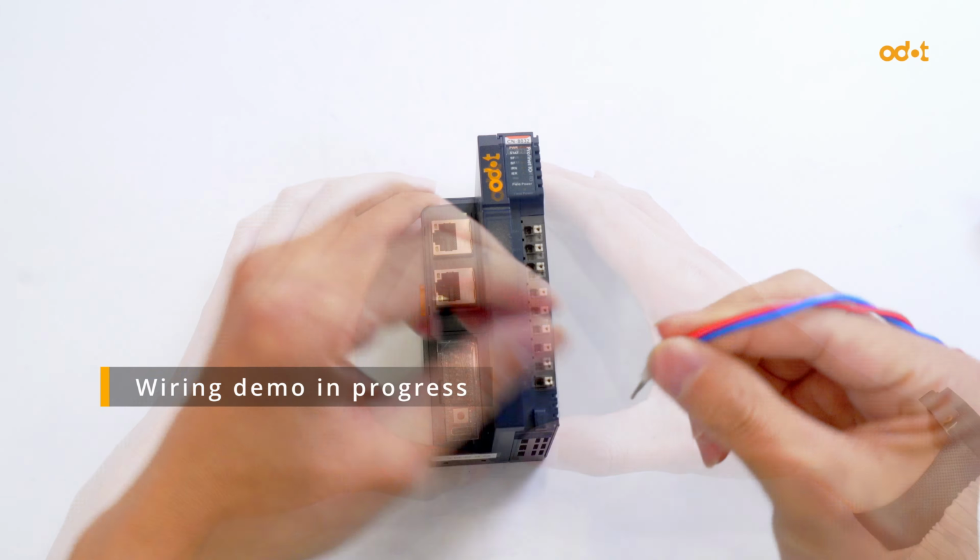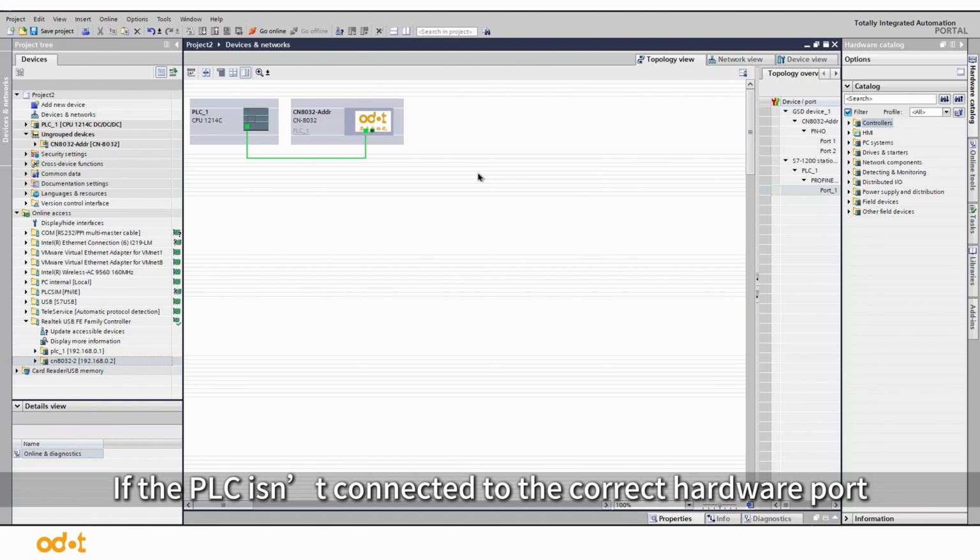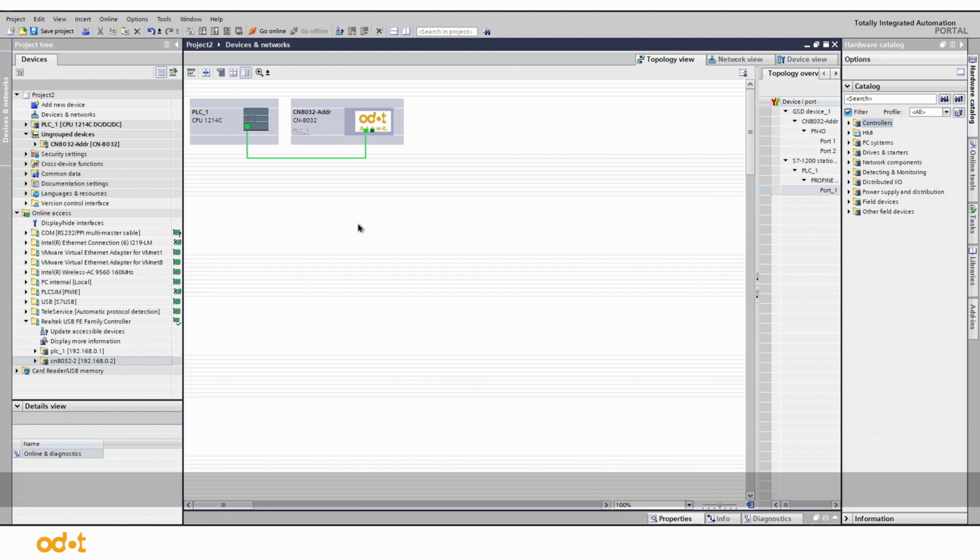Make sure the connections match the physical hardware exactly. If the PLC isn't connected to the correct hardware port, you'll get an error. If you only have one slave device, topology connections aren't necessary. But if you're working with multiple devices, it's better to set up topology connections. This ensures safety and reliable connections.